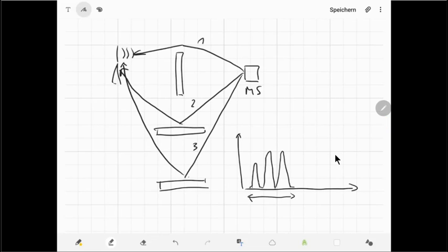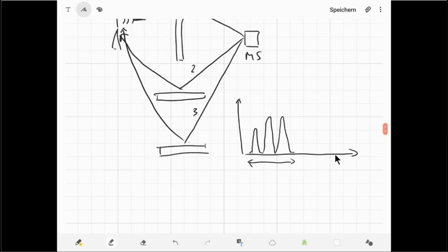And the receiver would then know that there are some obstacles in the way from the mobile station to the base station. And this is then further taken to process the received data and to take into account this propagation characteristics, so that at the end, with the knowledge of the training sequence, we can make the correct signal out of this received signal.